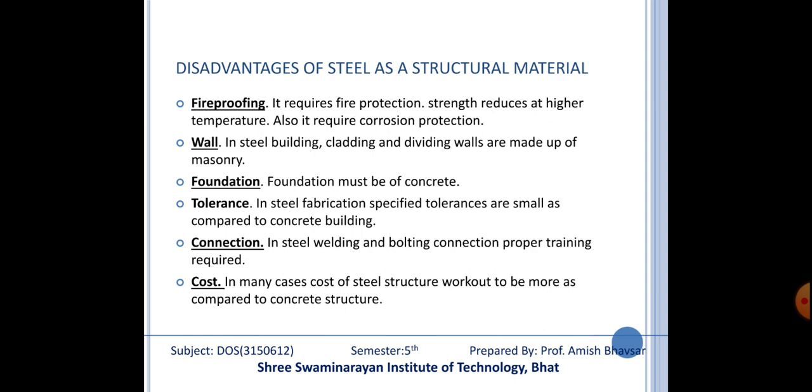But in some conditions, steel structure needs a number of members for stability, like a bracing system must be provided for resisting the wind force. In that case, the cost of the structure can be higher.